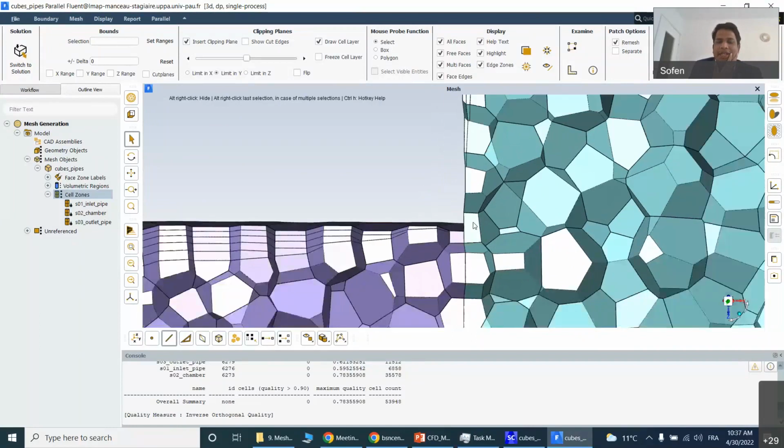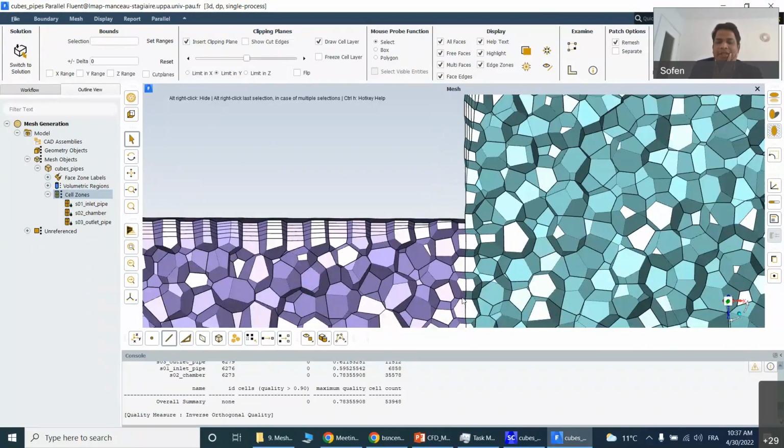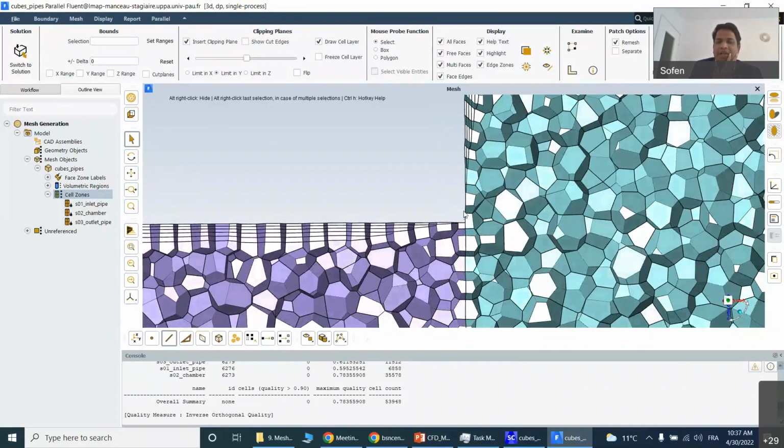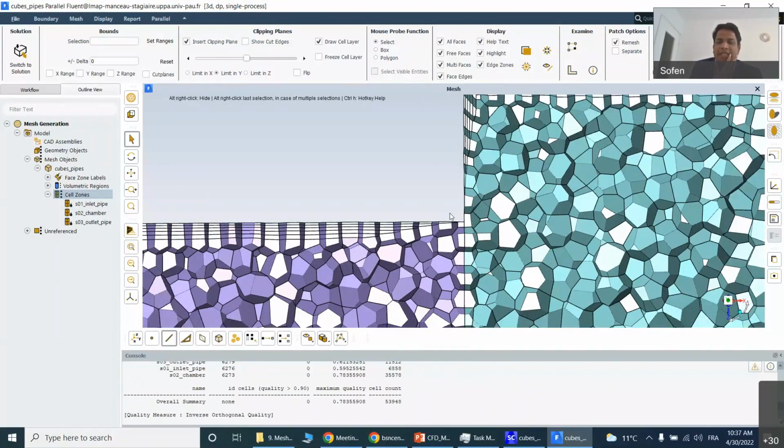So you need to take care. Even though generating the prism across the interface is a little bit computationally expensive, increasing the cell count, it is helpful so that there is not any place where an error is coming. Just like prism layer collapse, here you will get high turbulent kinetic energy, and if you are doing temperature, you will get a very unnatural hotspot over here, if the turbulent heat flux computation is not okay.